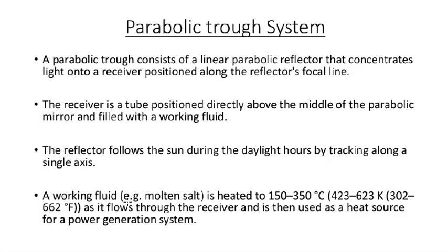This steam expands in a two-stage turbine. Between the high pressure and low pressure parts of the turbine is a reheater, which heats the steam again. The turbine itself drives an electrical generator that converts the mechanical energy into electrical energy. The condenser behind the turbine condenses the steam back to water, which closes the cycle at the feed water pump.